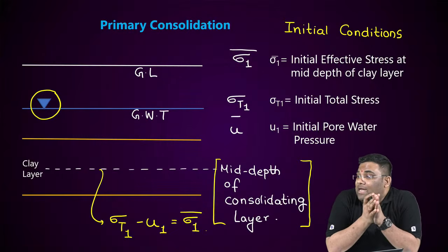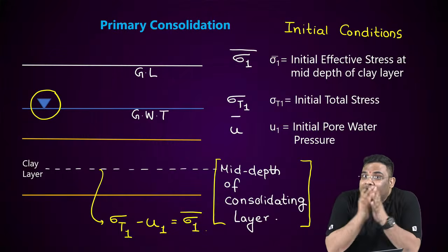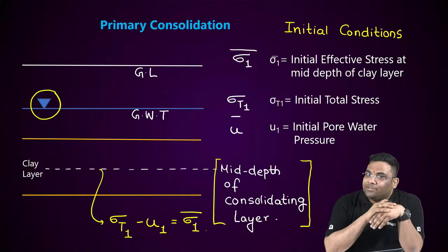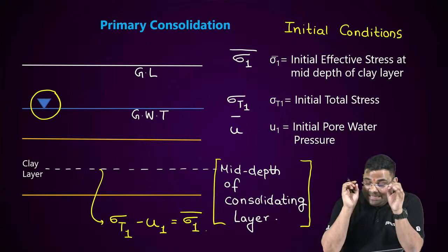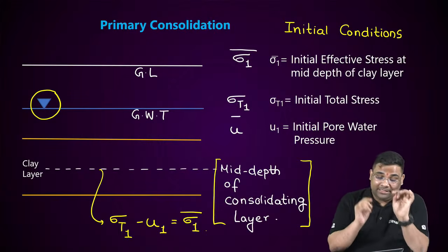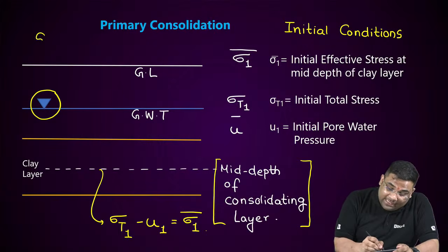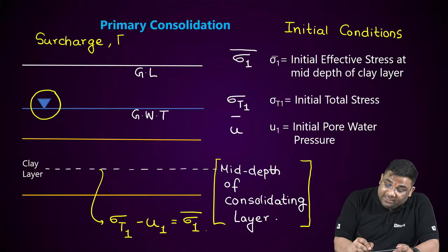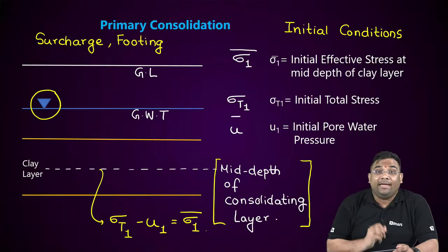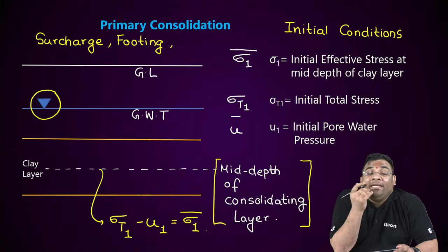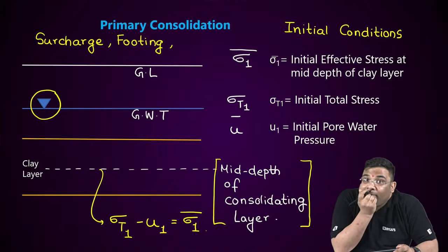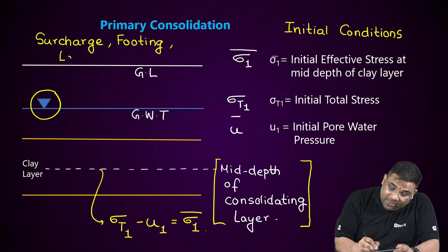See, surcharge is a correct answer, but give me all the reasons, or at least 2-3 reasons, right? We'll get this additional stress either due to surcharge, or if there is a footing or foundation load, or when there is lowering of water table.